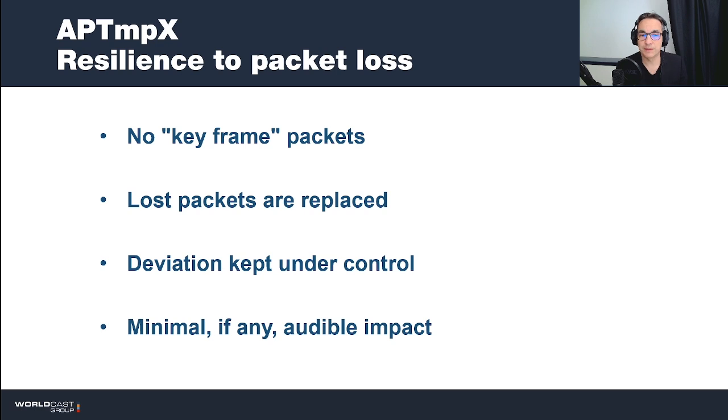Another point we mentioned before is the resilience to packet loss. APT-MPX has no keyframe in the stream, meaning that if you lose a packet, you will lose only the audio content that corresponds to that packet and no more.